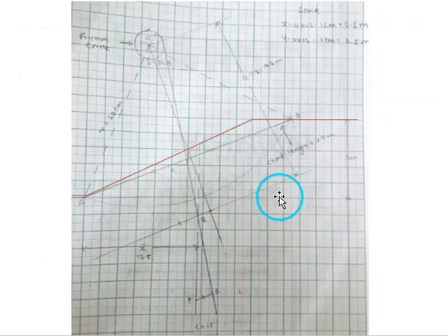So by taking 27 meter from this toe point, we can find the intersection point on the top of the embankment. That will become the other end of the arc. So knowing these 2 points, we can take the radius and we can find one intersection point, which is nothing but the center of slip circle. So after locating the circle, then we can take the r value, and from the center we can draw the slip surface. Then we can also find the delta value.